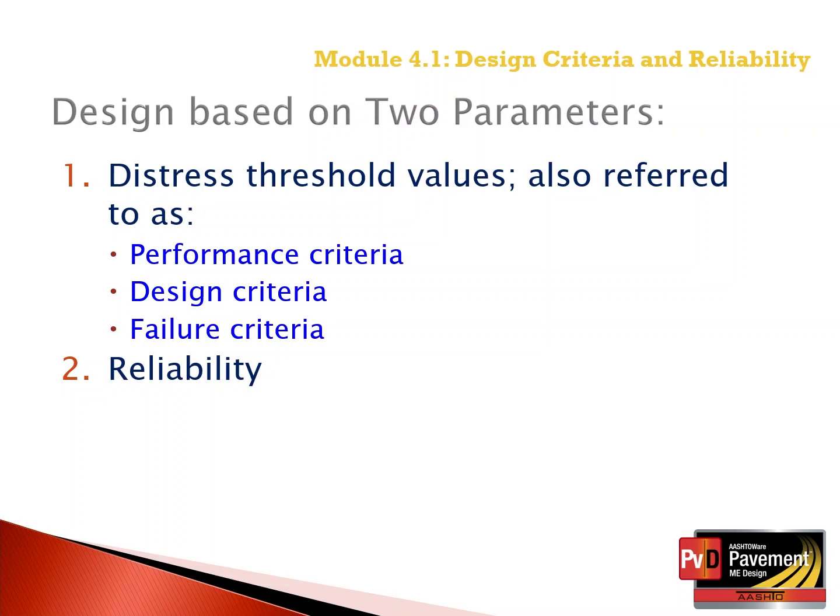Also, the user should remember that these distress threshold values should come from the agency's pavement management system, or how the agency operates and maintains its roadway facilities.